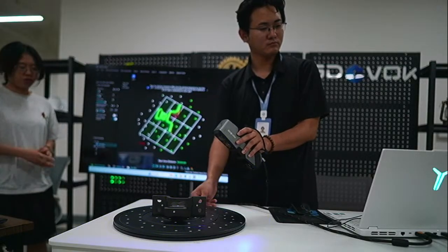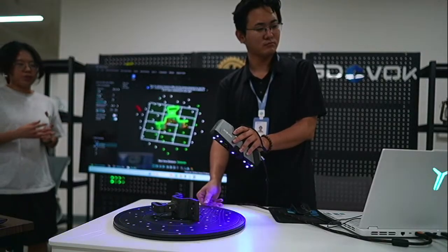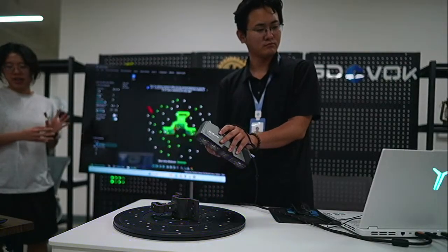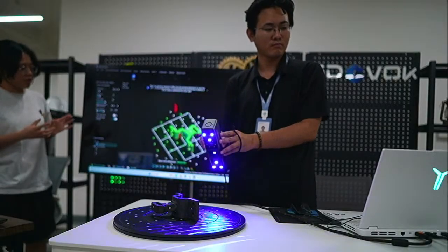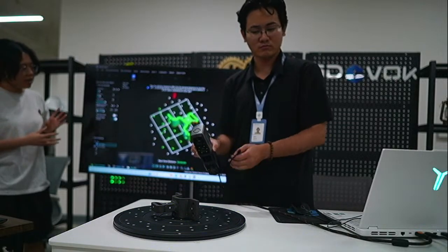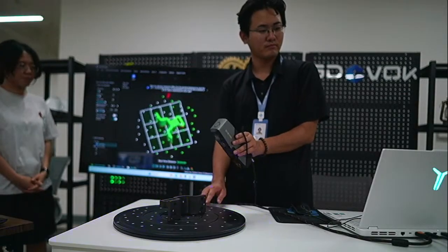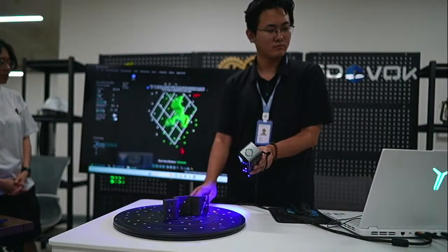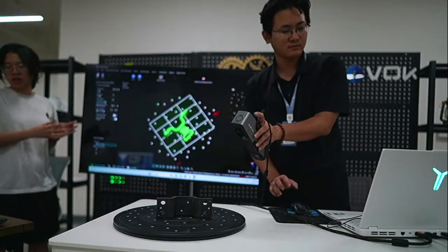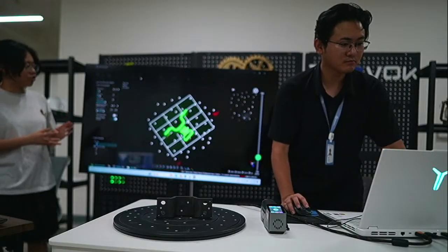During the scanning, we can observe the screen and the PC that you scan. So you can see we have opened the color map mode, and we are trying to make every area and every angle turning green, because we need a green color to reflect the high quality data that are enough to be processed to generate a mesh model. So when all the part turning green, we can stop the scanning, and then we can process to finish.